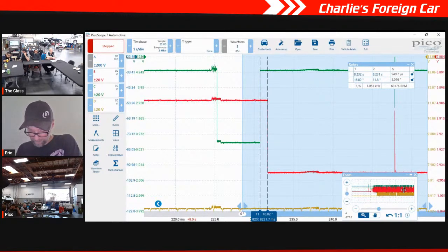If we advance the cam, roll it so it opens the valve sooner, you have to roll it away from zero, to get the valve open before zero comes over. And we're bringing it closer, so we're retarding the intake. Right, like Gianni said.